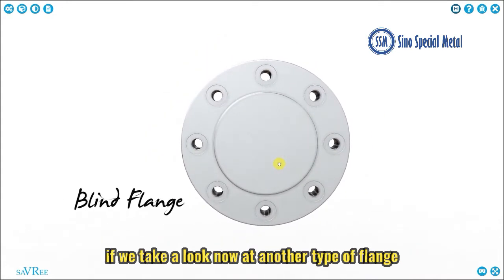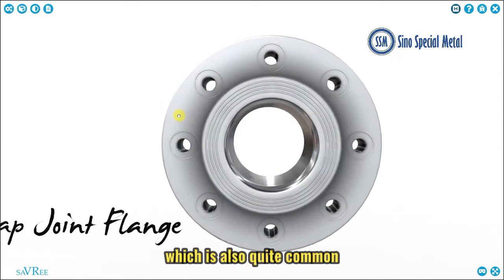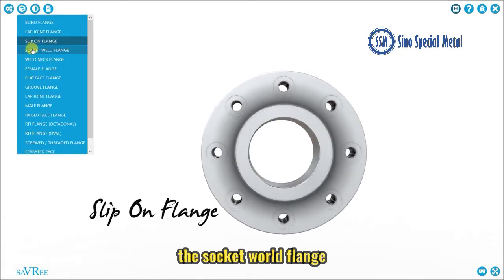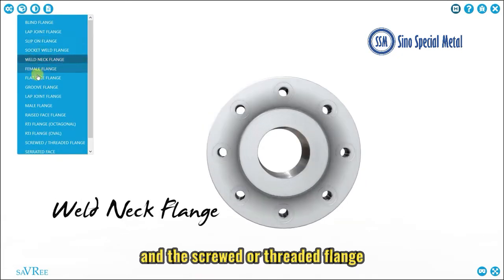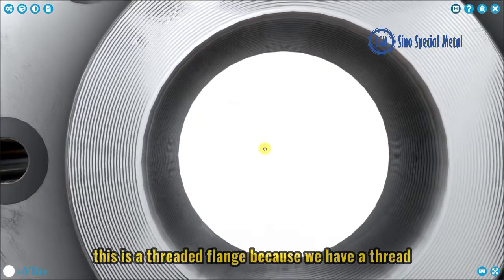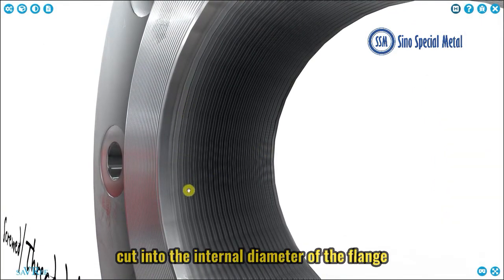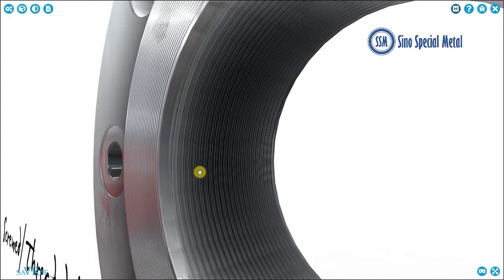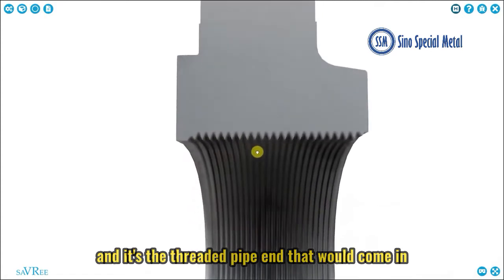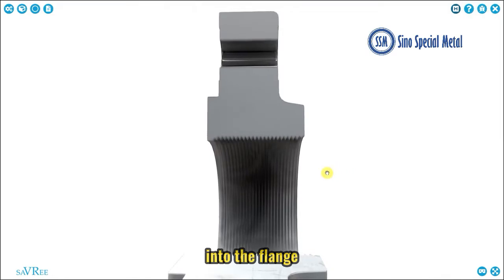If we take a look now at another type of flange, then we can take a look at the lap joint flange, which is also quite common, the slip-on flange, the socket weld flange, the weld neck flange, and the screwed or threaded flange. This is a threaded flange because we have a thread cut into the internal diameter of the flange. If we take a cross section, you can actually see that a bit more easily. And it's the threaded pipe end that would come in from the right and screw into the flange.